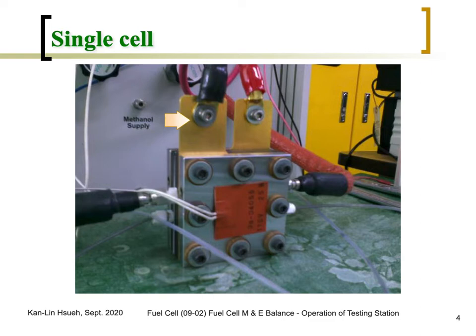We still use a big cable and contact to try to reduce any possible voltage loss. And we do not use an alligator clip, because an alligator clip easily rusts, and the contact area is much smaller, so it will generate a lot of contact resistance.